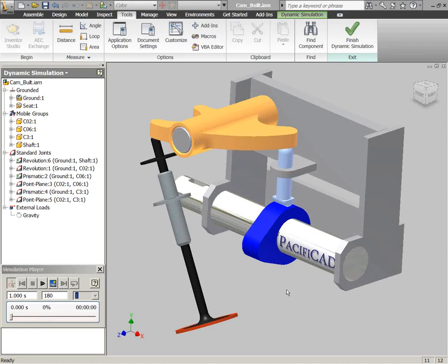All right, excellent. So basically what Jason did in the first part of this demonstration was to go through and create a cam that was going to give us the desired motion on the valve. And so his use of the simulation environment was to provide the exact motion of the valve that he wanted as it opened and closed, and then come back and create the cam from that. The next step that we want to do here is to kind of reverse that and force the cam to actually generate the forces that are going to be needed to cause the valve to follow that path.